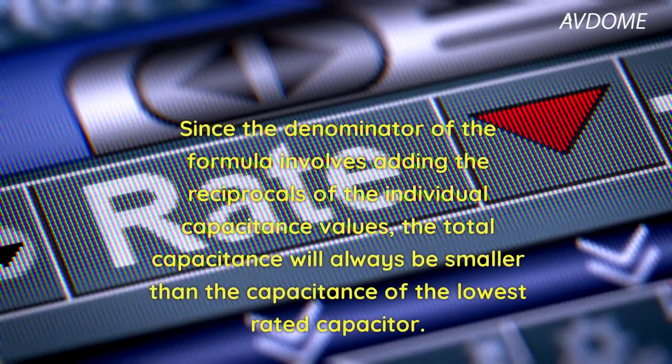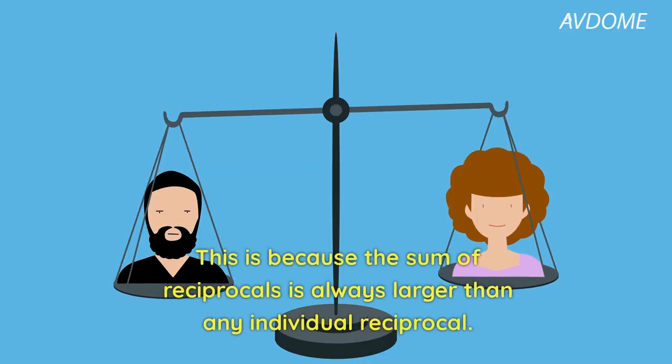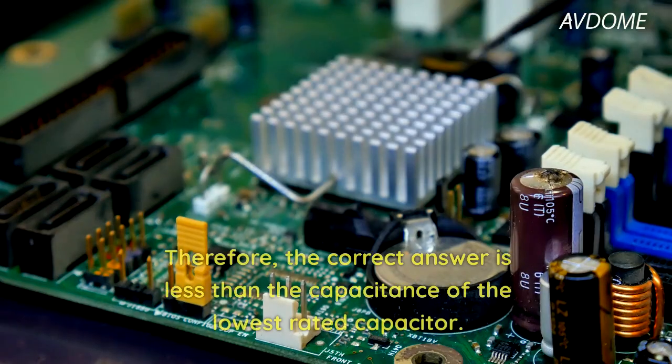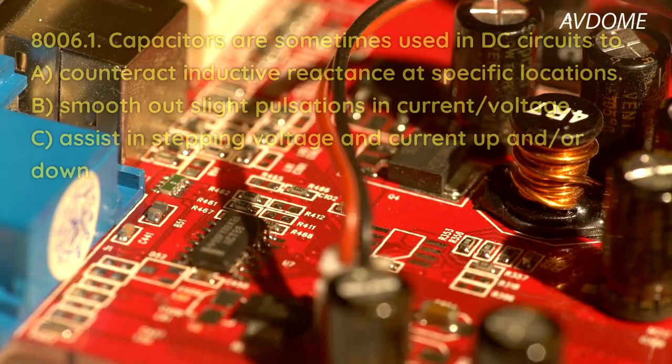Since the denominator of the formula involves adding the reciprocals of the individual capacitance values, the total capacitance will always be smaller than the capacitance of the lowest rated capacitor. This is because the sum of reciprocals is always larger than any individual reciprocal. Therefore, the correct answer is less than the capacitance of the lowest rated capacitor.